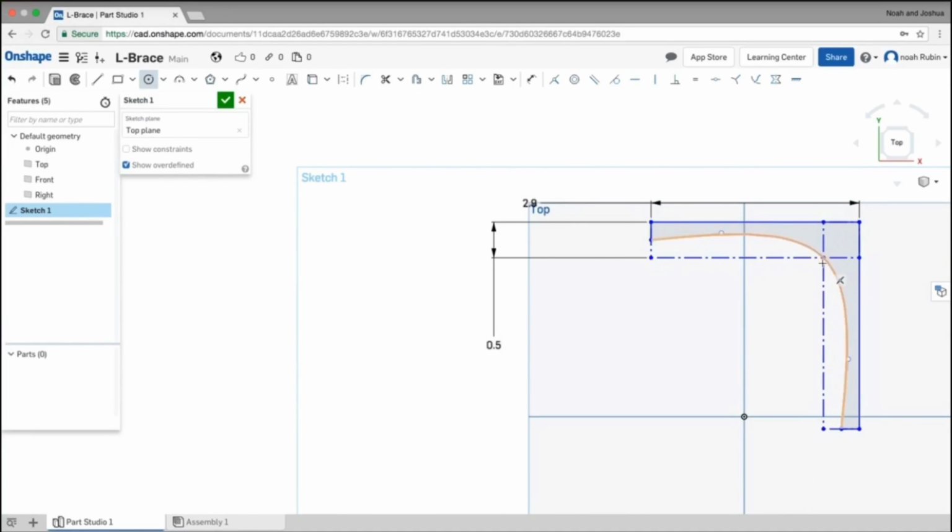I'm just going to add a small little circle to show you guys more construction tips. We'll make the diameter of that 0.75, and then we can either use the trim tool over here and just cut out the lines, or we can press construction and press on this.